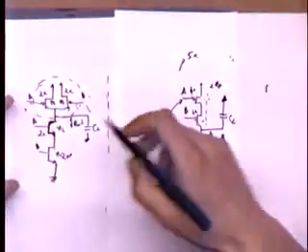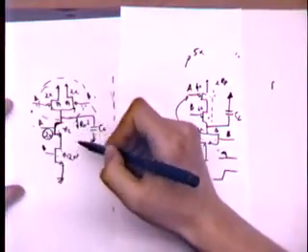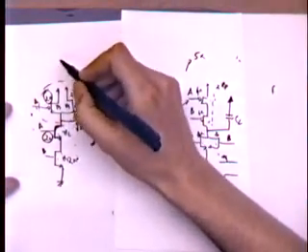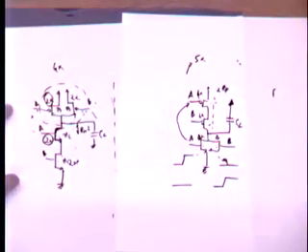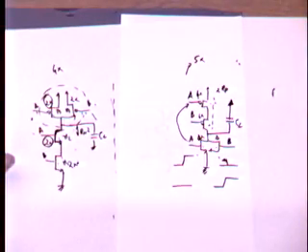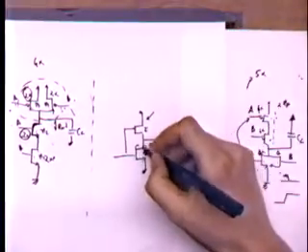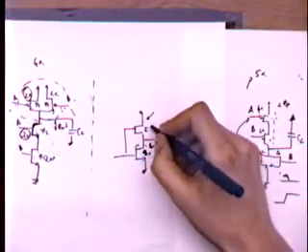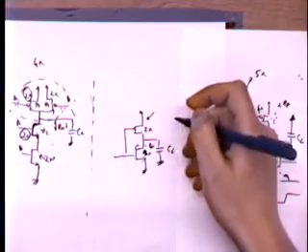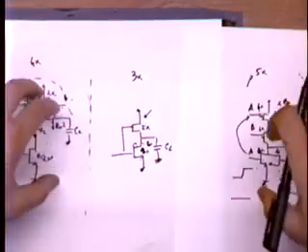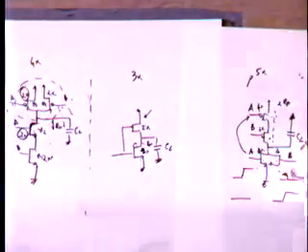Whereas the NAND gate has a 2x NMOS and a 2x PMOS, and therefore the input capacitance is 4x, where x is just the input capacitance of the unit transistor. And remember, the inverter has a capacitance of 1x for the NMOS and 2x for the PMOS, so the total capacitance is 3x. All these three gates have the same driving current ability, so they have the same equivalent worst case on resistance, okay?